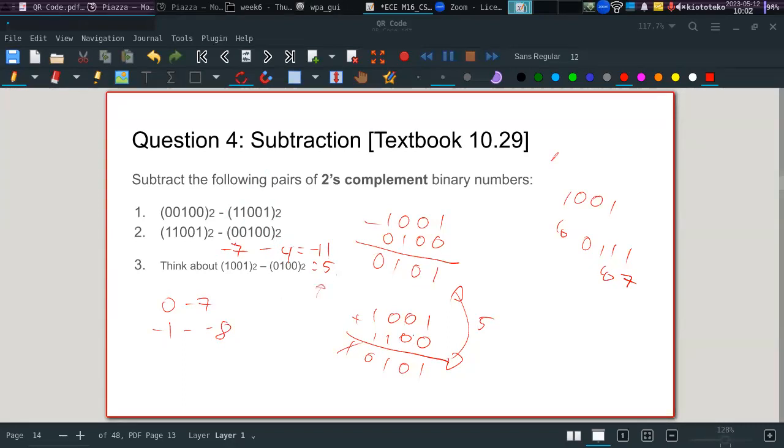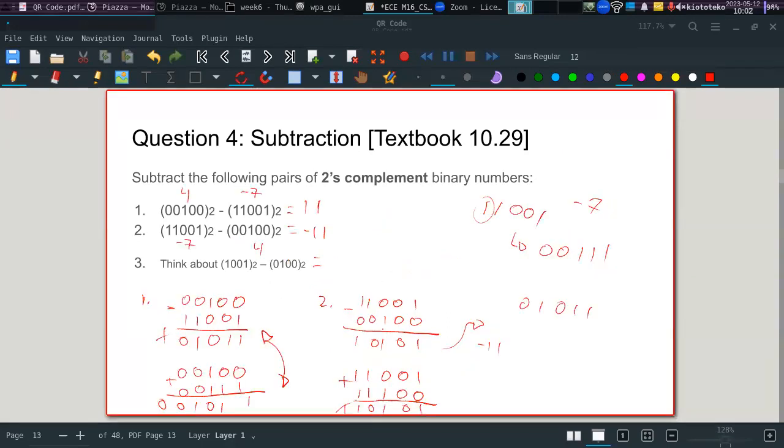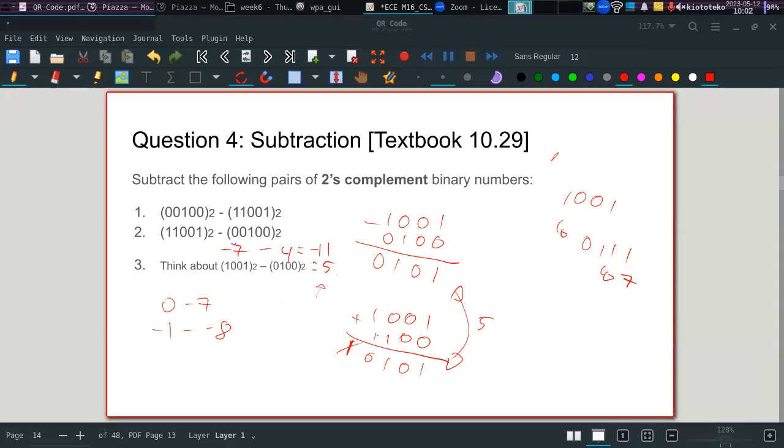Here, no? In fact, if we do the addition using two's complement, you can see that we are getting the correct result if we consider the 5 bits, no? Because it is telling us that this overflow is 1, which means this number is negative, no? And if you remember, this was indeed -11, no? But because we are operating over 4 bits, we don't get this information. And if you do the subtraction normally, you won't even notice that this is a negative number, no? Because there's no overflow. That is, I guess, one advantage of two's complement. At least you get the sign of the result in these cases.